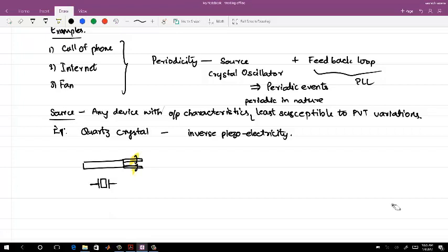And the electrical model for the crystal means you can model all these oscillations using an inductor and a capacitor. And the electrical model for this is C0, L, R, C1. So though this is a mechanical device, you can model the oscillations which are happening in this device with the inductor and capacitor. And the resistance is basically telling that there are some losses in the system. If you stop giving the current to the crystal oscillator, it will lose the oscillations.